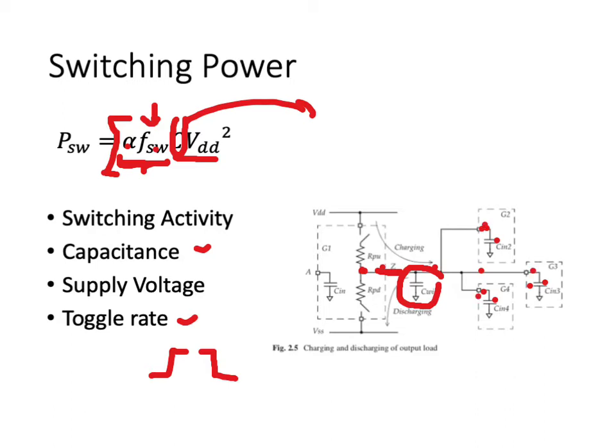That means the output of the logic gate, which connections are made to the inputs of which logic gate. You need to know the type of logic gates being connected at the output, as well as the logic gate itself that is under study. And you need to know the length or the capacitance parameters of the wire, and you need to know the size and the timing properties of individual logic gates. So these can be extracted from the post place and route netlist.